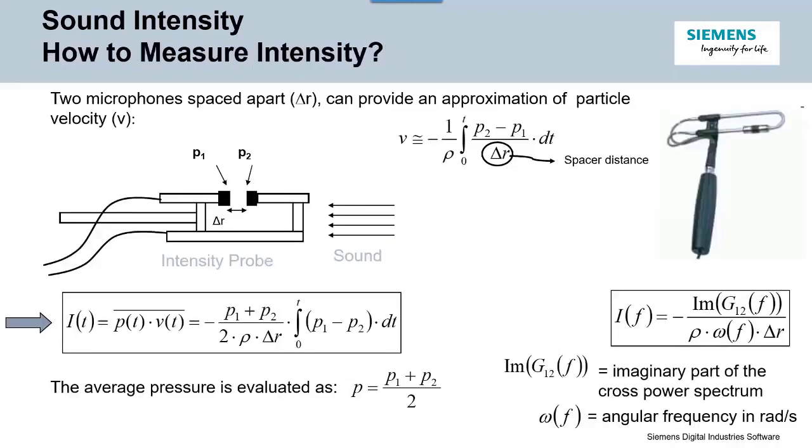So let's see how to measure sound intensity. For measurement of intensity, we need 2 quantities: one is the sound pressure, and the other is the particle velocity. There are some probes out there, like a microflown probe, which measure particle velocity. When you do the intensity measurement, you directly get the intensity based on the sound pressure and the particle velocity. But many times they are delicate equipment.